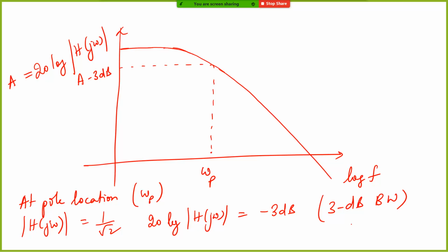See, because it is going to continuously reduce as you go up higher in frequency. To give an example, if you look at the common emitter amplifier that you have designed, let's say at 1 kilohertz you'll have some values, right? At 10 kilohertz you'll have the gain which will be slightly lower, and at 20 kilohertz it will be even more slightly lower. And as you go higher up in frequency, let's say 40 kilohertz, 50 kilohertz, 100 kilohertz, 200 kilohertz, gradually the gain starts dropping.